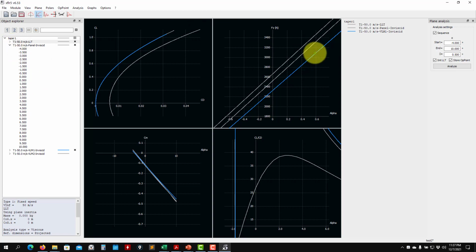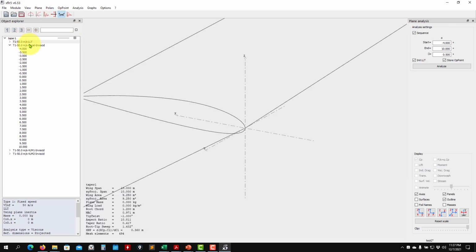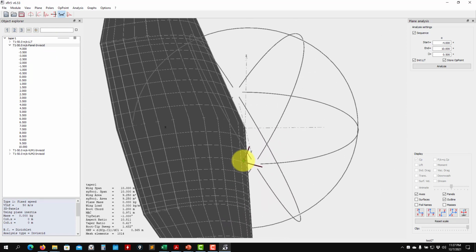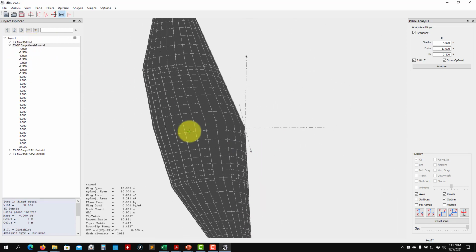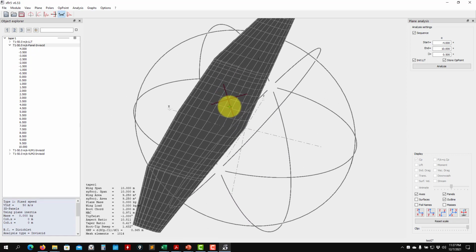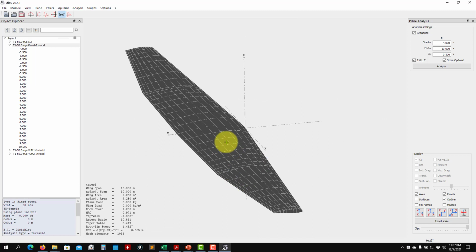Finally, what I want to show you is you go back to the airplane here. So this is the actual paneling that you are resolving when you use the panel solver in XFLR5. If you want to change the paneling, it is not recommended, as I say, to put in a million panels. There is no need. Some stuff like this proposed automatically is okay.